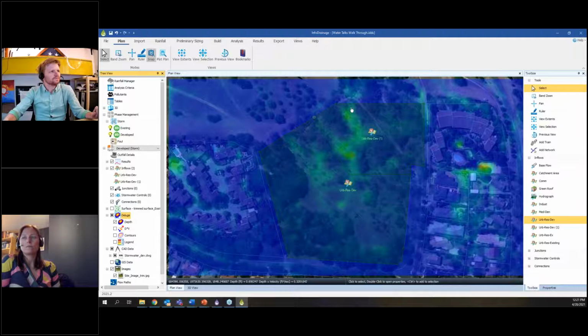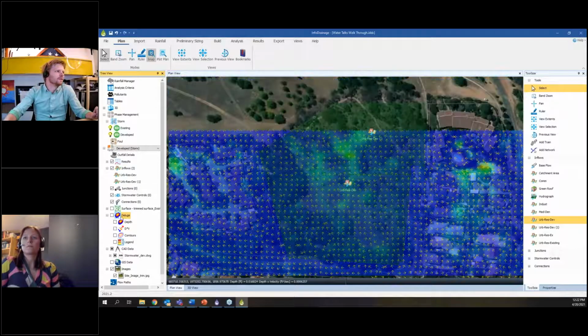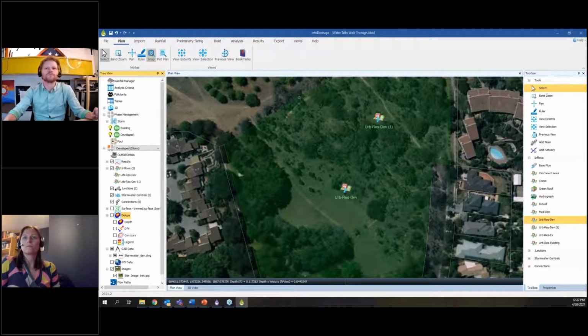Throughout this middle, this green area is representing higher depths where the blue area isn't. The hazard areas also kind of help give you a framework, and generally things seem to be flowing down into this middle area, starting here and then down through the bottom. So that's where I'm going to start my bioretention cell, and then use a pipe network to get down to a dry basin to mitigate the main part of the peak flow.